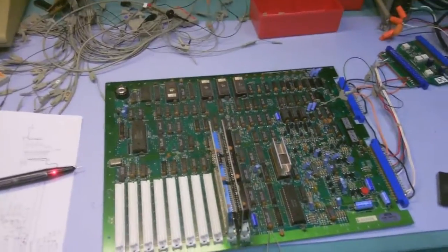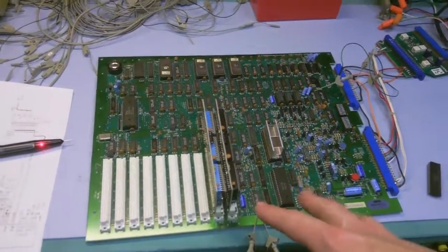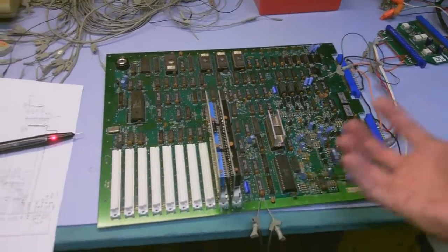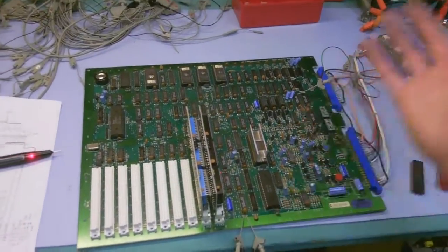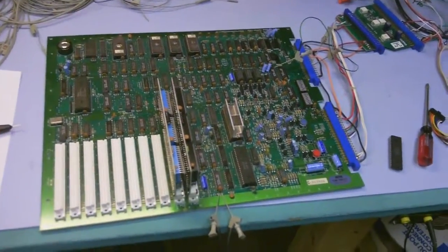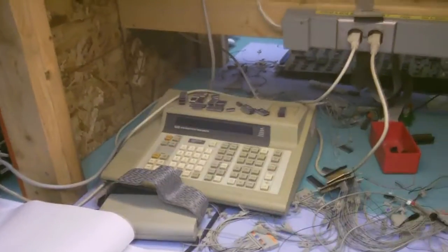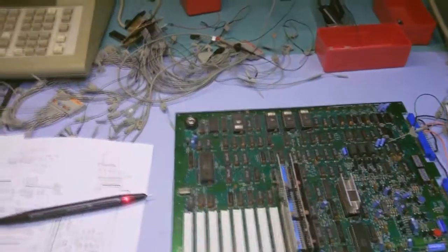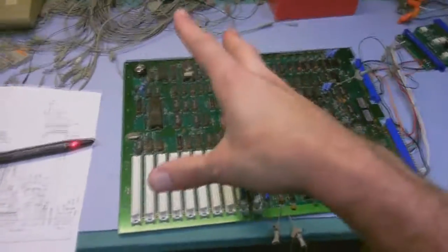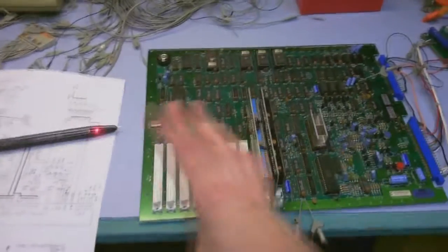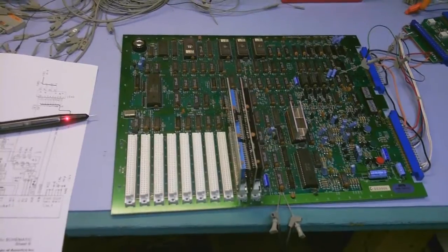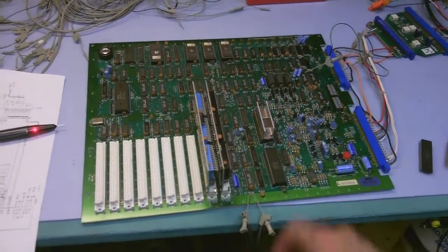So I'm going to go ahead and see if I can force this into a gameplay mode, because otherwise I have to wait for the menu to constantly select this CPU to actually see some activity. I believe when the menu is up, this is just held in a constant reset, and that's no good. I got to be able to probe the thing and see what's going on. So luckily I have this guy, and so I can stick my Z80 pod on there and let it run through the menu sequence, and then once it turns control over to this guy, freeze it, and this guy will just continue to run the show, and he can drive it. So let me start with that, and we'll see if we can figure out what's going on over here.